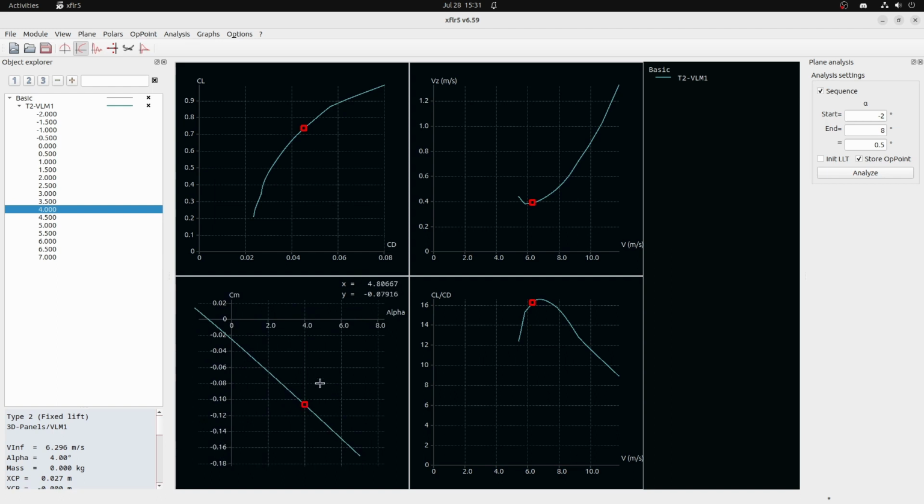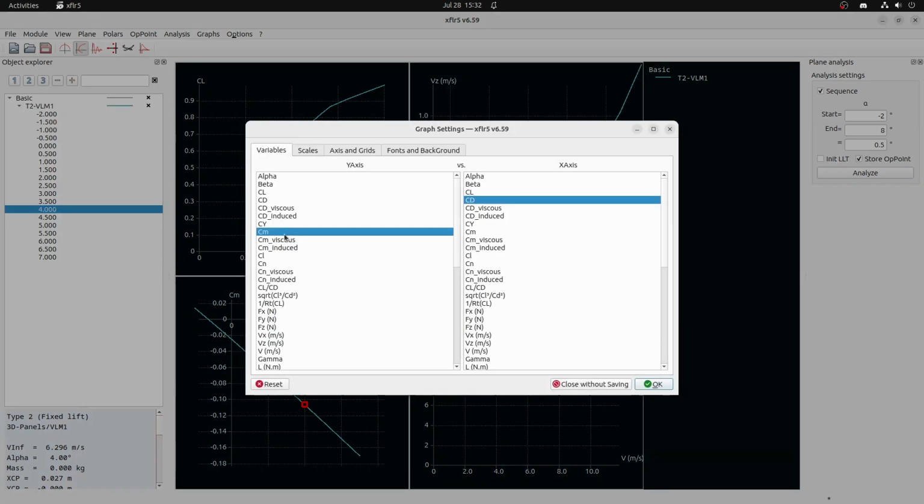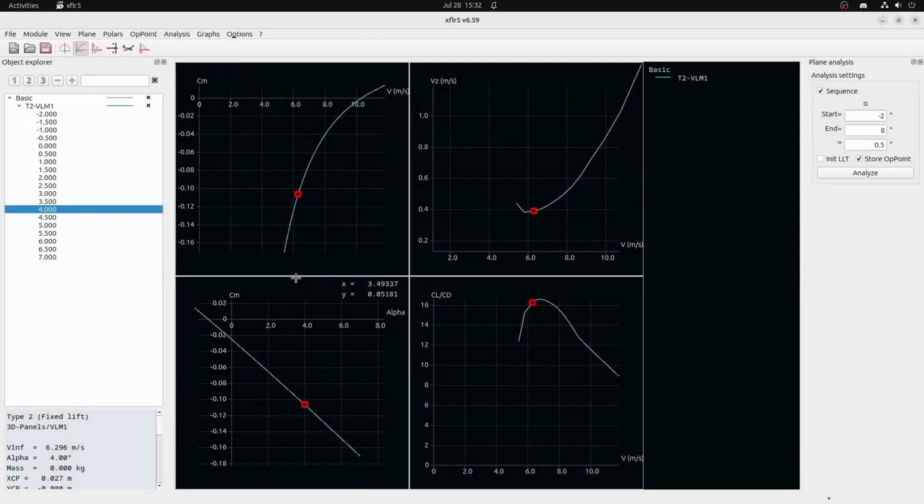If the slope of the line was an increasing one, and we're at an angle of attack of, say, 4, and a disturbance pushed it up to 5, then the aircraft would want to nose up, and it would be unstable. We can also plot the pitching moment against airspeed. It's interesting because if we look where there is zero moment, that is, when the aircraft neither wants to tilt up or tilt down, it's the airspeed where the aircraft would travel on a level path with a neutral elevator setting. You can see this is occurring at just a little over 10 meters per second.